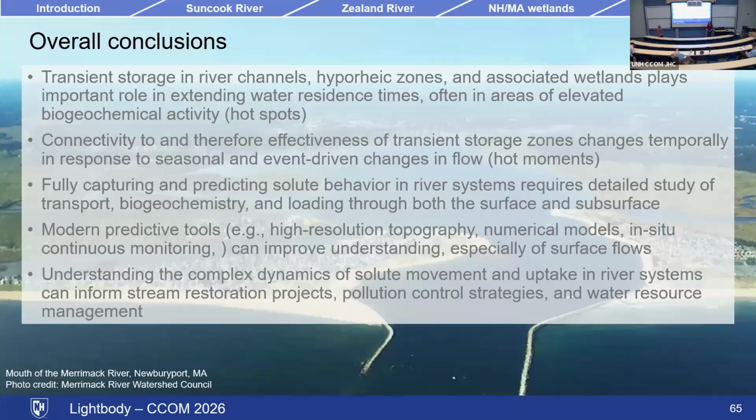Which is that variable? Is it the longitudinal distance from A to B, straight line? So I guess when we're thinking about distance, it would be the meandering distance. So it would take into account the straight line times the sinuosity of the river. Okay, so you're right that if other people are reporting it differently, that maybe is why we're getting some additional scatter in our curves. Okay, it would be useful to point out that you are measuring the actual length.